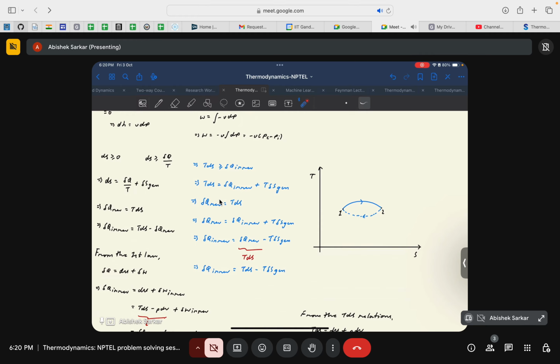Again, this is not the process inequality. But this is the equation that we have mentioned, that for an isolated system, the net change in entropy is always greater than or equal to 0, and the relation between the change in entropy and the ratio of heat transfer by temperature is usually given by this equation, where this is equal to del Q by T when the net heat transfer is done in a reversible manner.